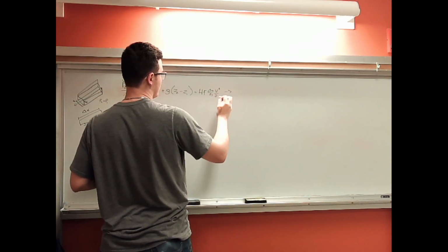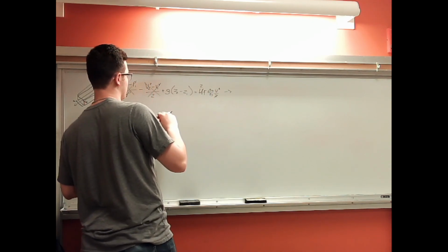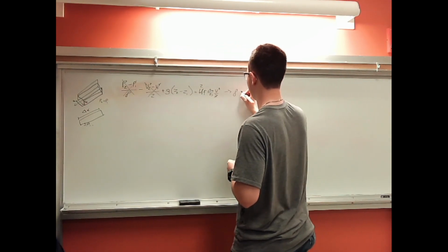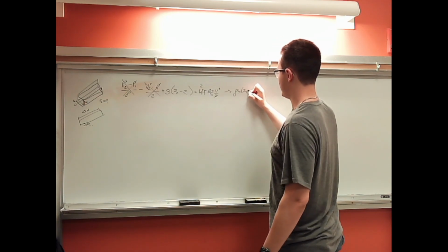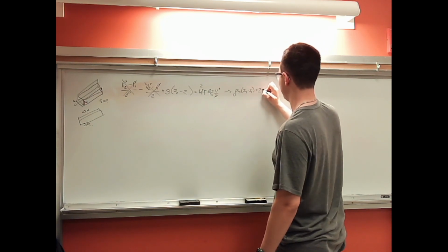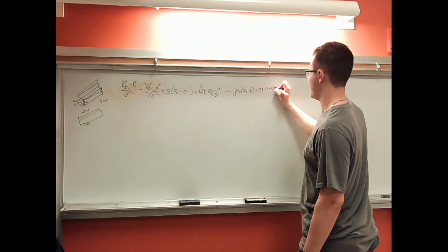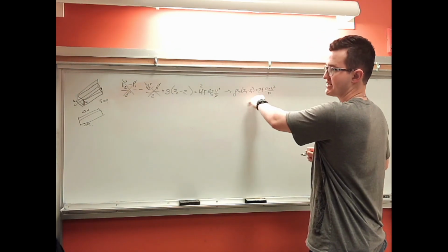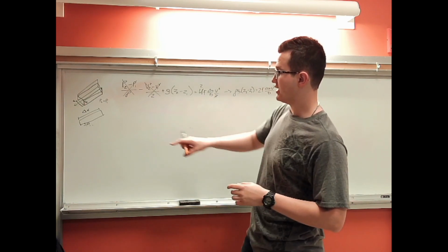So this is going to go to rho, the density, times gravitational constant times z2 minus z1, equals 2 times the Fanning friction factor times delta x, the length, times the velocity squared divided by the diameter. Now this z2 minus z1, the difference in y positions in state 2 and state 1, is actually hidden here.